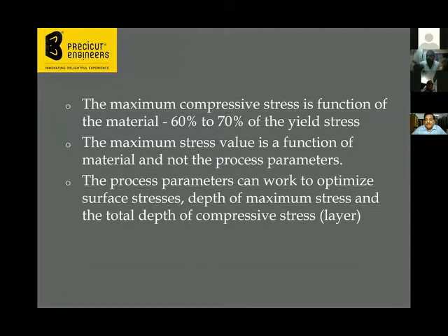We can induce only up to 60 to 70% of the compressive stresses in terms of the yield stress of the component. So the maximum stress is a function of the material, the yield stress of the component, and not the process parameters. Where the process parameters come into the picture is to optimize these results. By manipulating them, we can achieve the desired stress. We cannot exceed this stress.